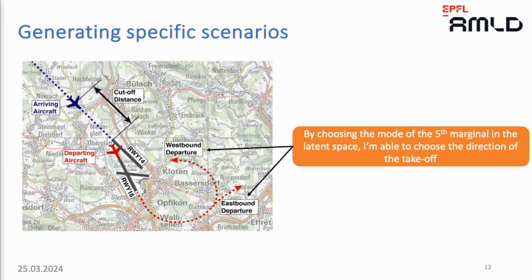Here, we've chosen VAE over GANs, for instance, or normalizing flows, because in VAEs we have ways of evaluating the likelihood of the distribution we are estimating within the latent space. And this is very useful in the following work, when I'm estimating the risk of collision, because I want to use a fancy algorithm that necessitates estimating the likelihood of the samples I'm using. So the VAE has a probabilistic structure that is very suitable for the other algorithm I'm using for estimating the risk of collision.